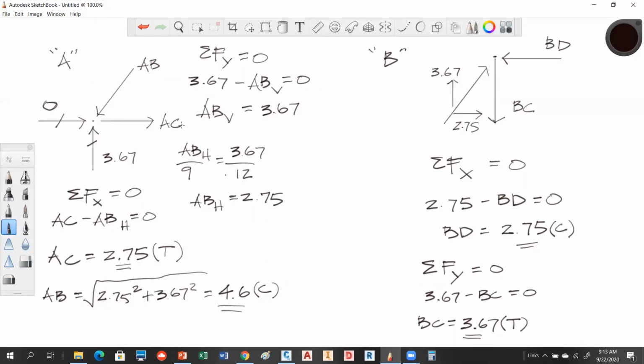Those are feeding into the joint C. So you actually know two of the members coming into that, so you only have two unknowns essentially. So C would be good, yes. At joint D, the only thing you would know would be member BD, and that would not be enough. You've got those two diagonals and one vertical on the joint D. Just too much unknown, right?